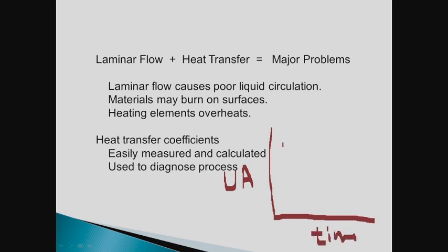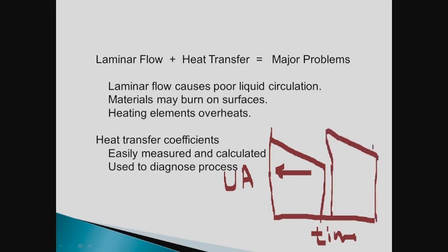And what you can do is, over time, denote the drop in the heat transfer coefficient over time. At some point, the performance becomes unacceptable, right? And you decide that. So then you go down and clean, okay? And the cleaning is going to take a little bit of time. And suddenly you're boosted up here, and then you come back down, and then you do some cleaning again. I guess you got to go way down here.